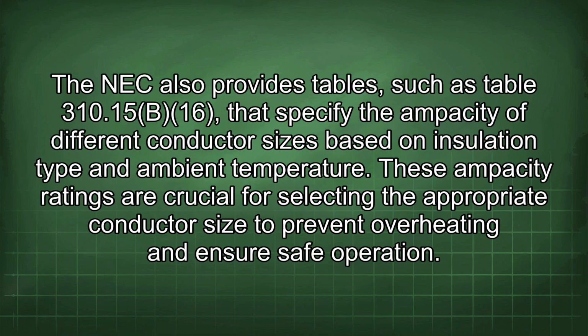The NEC also provides tables, such as Table 310.15(B)(16), that specify the ampacity of different conductor sizes based on insulation type and ambient temperature. These ampacity ratings are crucial for selecting the appropriate conductor size to prevent overheating and ensure safe operation.